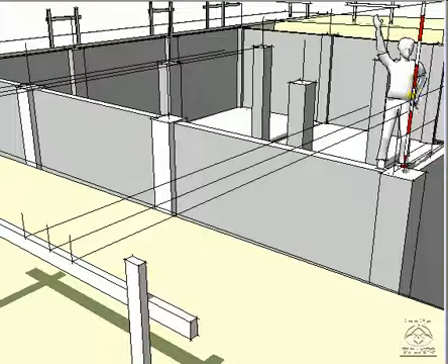That would mean the bottom of the beam would be 41 inches below the string line: 36 inches down for the height of the string line off of the reference, plus 5 more inches to the bottom of the beam. So since the height of the string line anywhere between the batterboards is the same elevation, the bottom of the beam can be measured as 41 inches below any string line.